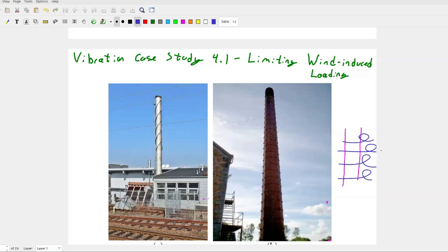It's a vibrations class. Why does it matter? Those vortices introduce small loadings onto the smokestack. We consider a lot of times wind to have a lot of different frequencies in it, a lot of different speeds. When wind hits the right speed, it will hit the right resonance of that stack. And because that stack is one diameter the entire way up, it will all start to put energy into the system at that resonance, and the whole thing will come crashing down.